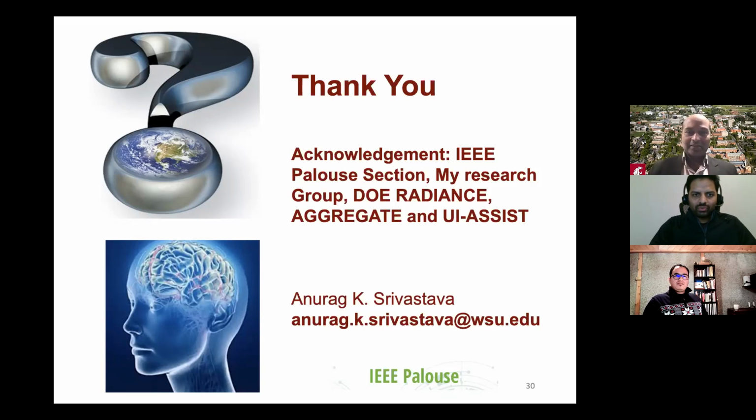So how to interpret it if one microgrid has 70% resiliency? What should we understand if someone says a microgrid has 70% resiliency? That's a great question, and something I'm asked often. Just by looking at one number, I cannot tell much. If I increase my battery capacity, it's going to be 75. But if I change my manually operated switch to a remotely operated switch, like the switch example I was talking about before, that will increase my resilience to 80%. So where to invest? Maybe the switch, not the battery. So those kinds of questions can be answered. It's a relative resiliency.